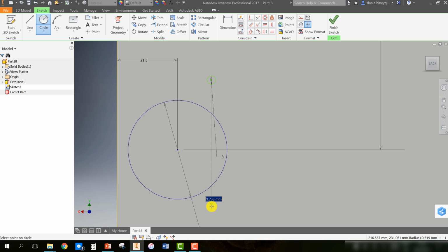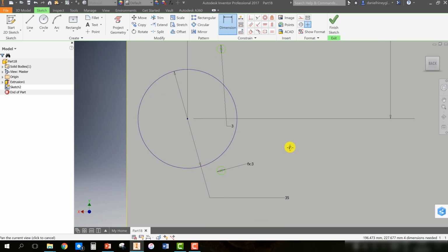We have this set up now, so we're going to set a dimension on that, and the diameter is going to be the same as before. So we're going to go to list parameters, and small diameter is here, 3 mil. Okay, perfect.